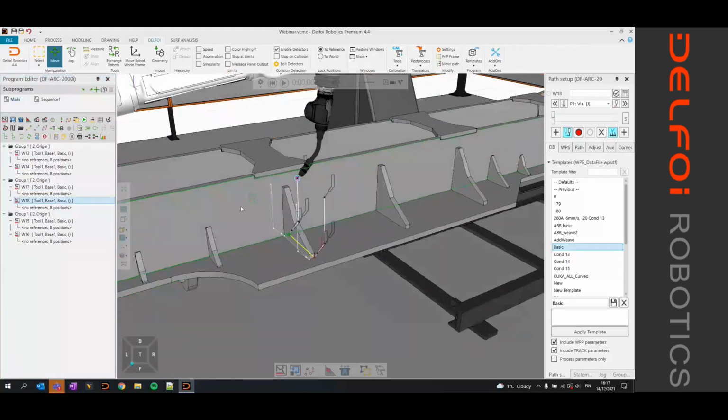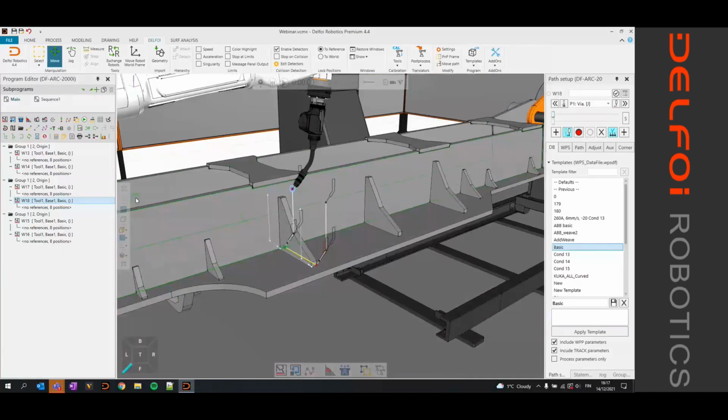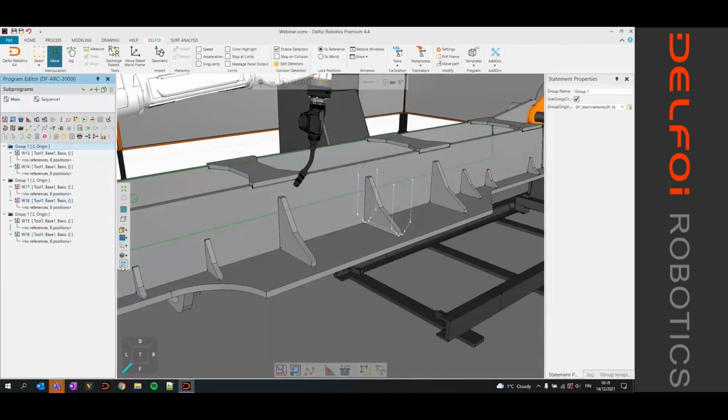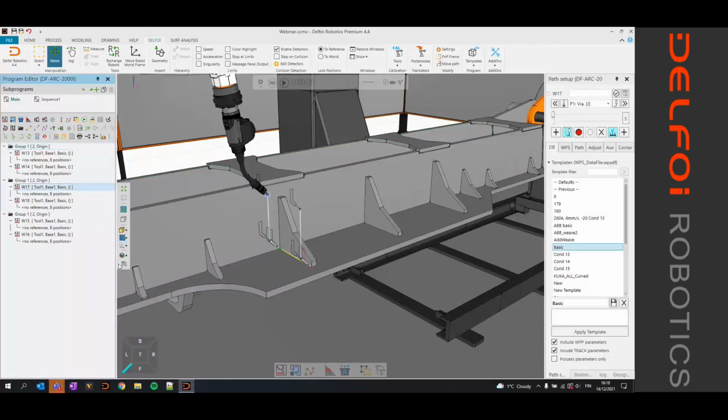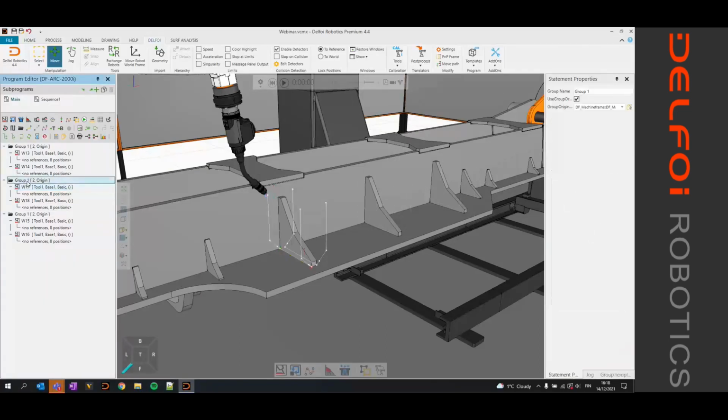And in the end, we will end up with 3 groups now in our program, where we can then toggle our visibilities for each group with selected mode, all mode, only subprogram, and only the current active group with the scope statement.